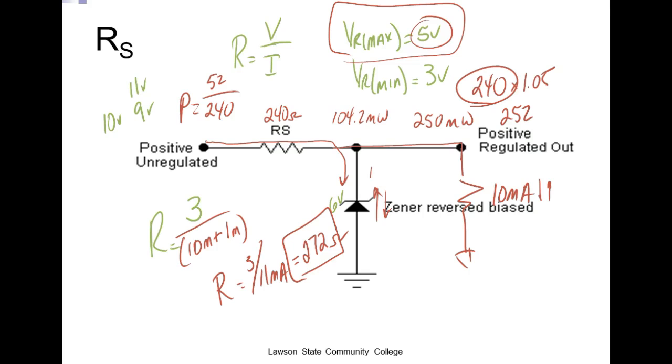So we're looking at Zener diodes. And then what do we do? We calculate the resistor. Then what's the next thing we did? Somebody tell me. We looked it up on a standard resistor chart, right? What did we always do? Round down, because this guy right here is going to sit at the knee. We round down, so that moves us away from the knee.